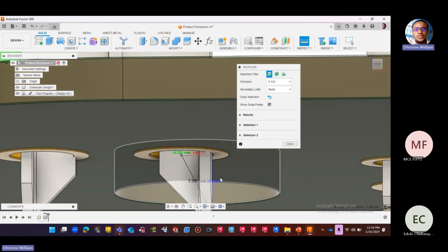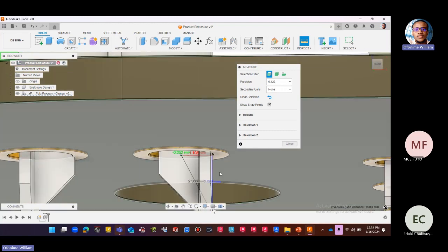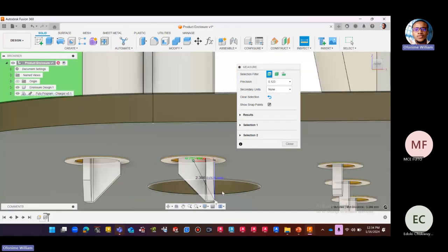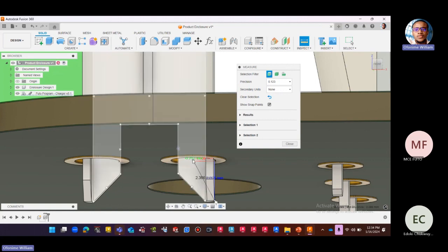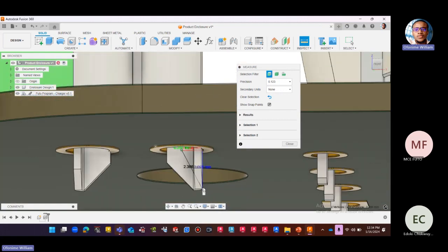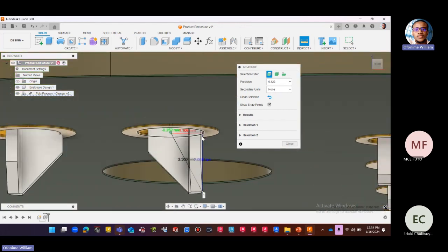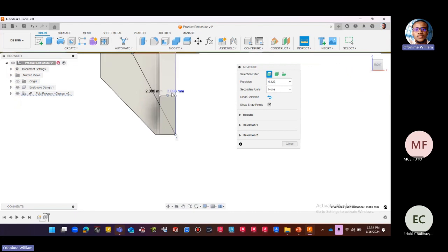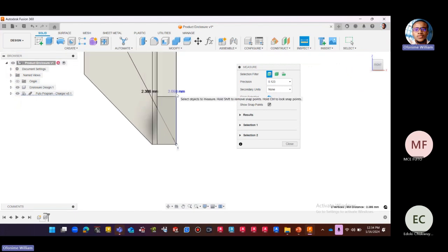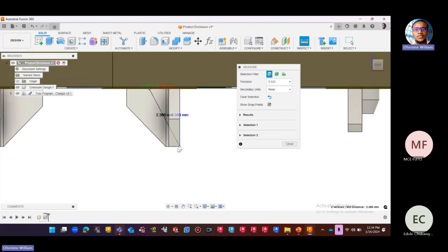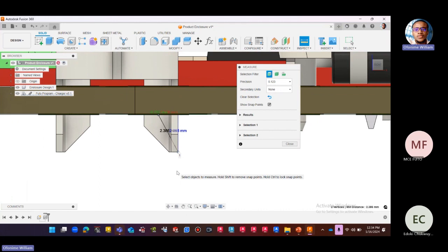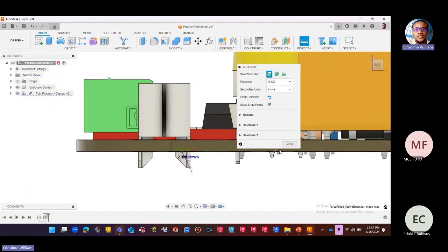So now you could really see what that delta kind of measurement is doing. The first one is going straight, the second one from that straight point to the left, and the third one. So it's a 3D kind of measurement now. But what are we concerned with? The blue one, right? That's the one that is going on the vertical axis. So this measurement reading, 2.098, is the reading that we require, from the board to the highest component below. So I believe that is understood.